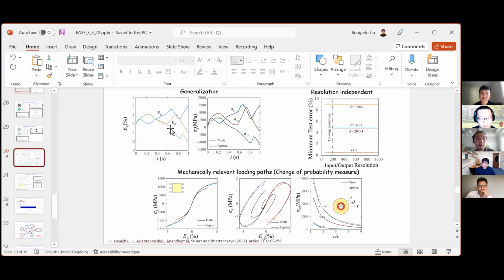Now, talking about geometric nonlinearities, we use a general framework where we pass in the deformation gradient. And again, in our data, we have this microscopic Cauchy stress. We can use Piola-Kirchhoff stress, but we use this Cauchy stress instead. That's how we embedded the geometric and material nonlinearities in our model, by learning from the data. Okay. Thank you very much. Thank you.